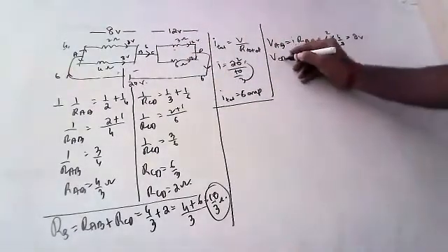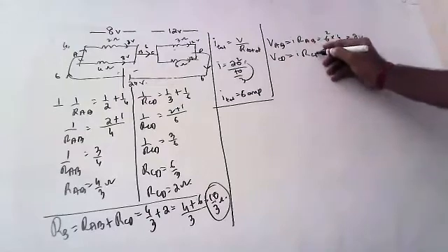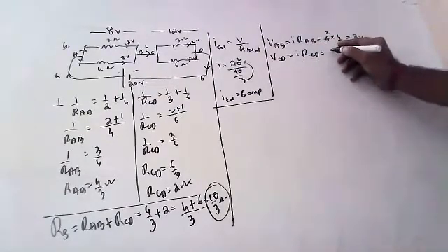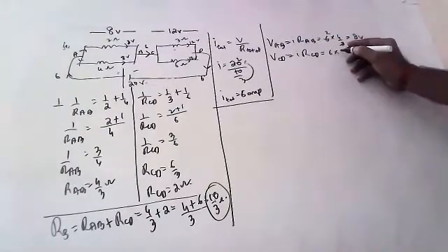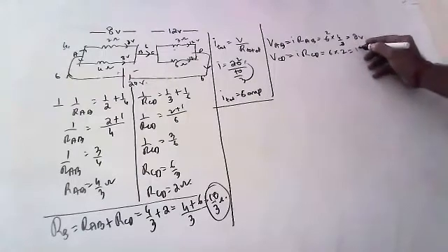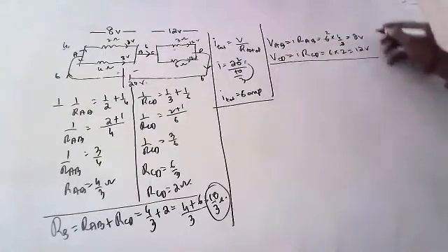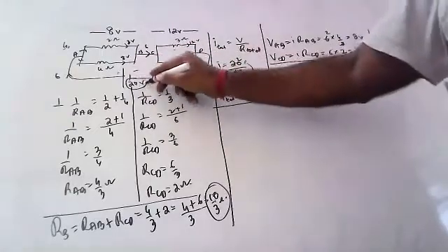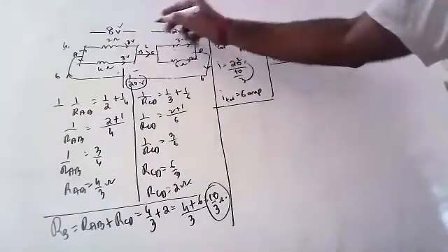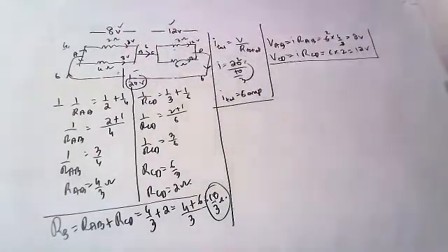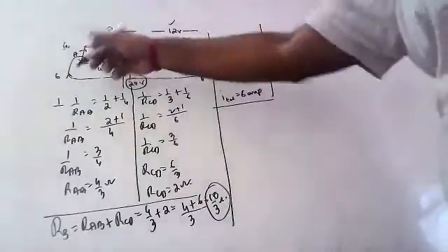Okay. So VCD is equal to I RCD. I is how much, children? 6. RCD is how much, children? RCD is 2. So 12 volts. I already told many times. So the total potential of 20 volts is shared as 8 and 12 by these both junctions. Now we will find out the individual currents, children, how the current is dividing here.